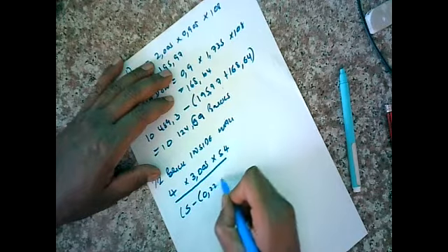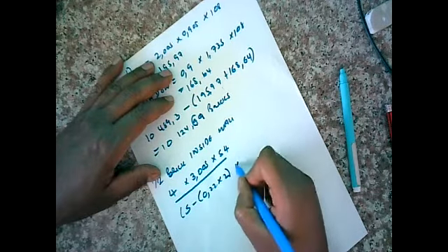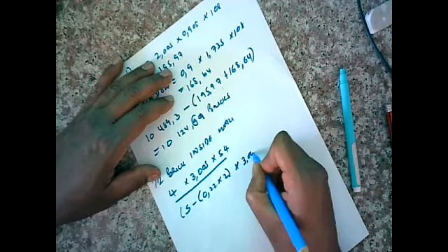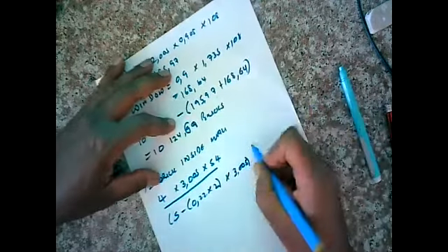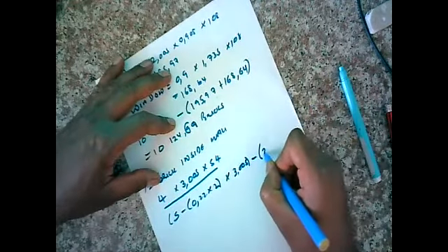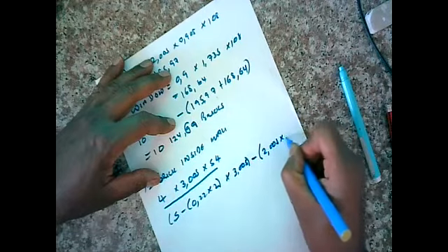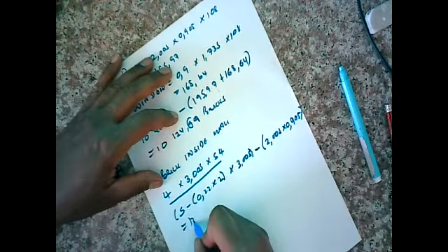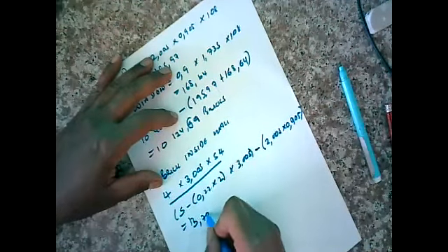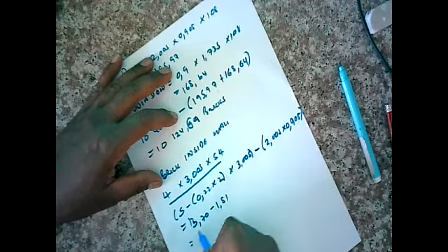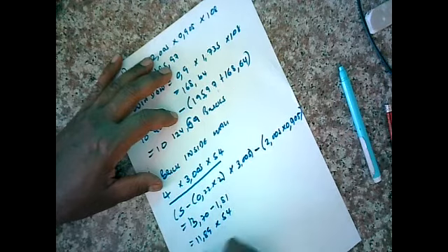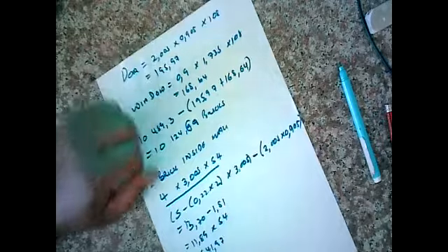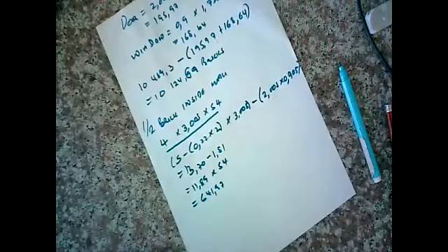Subtract 0.22 times 2 times the height of 3.05 minus the area of the door, which is 2.005 times 0.905, and we get 13.70 minus 1.81, and we're getting 11.89 times 54, because it's a half brick wall inside, 641.97 bricks for that inner wall. Now we're done with walls.